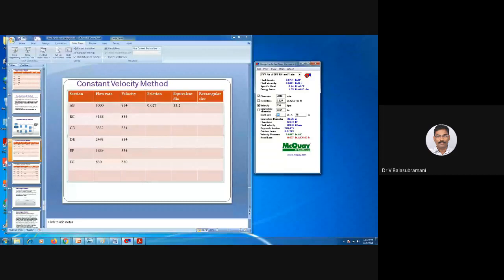So the height of the duct should be increased. If you use 66 divided by 16, the aspect ratio is once again 4.125. So the duct size is maintained as 18. So 56 divided by 18 is equal to 3.11. Here the aspect ratio is very important. So the rectangular size is equal to 56 cross 18.